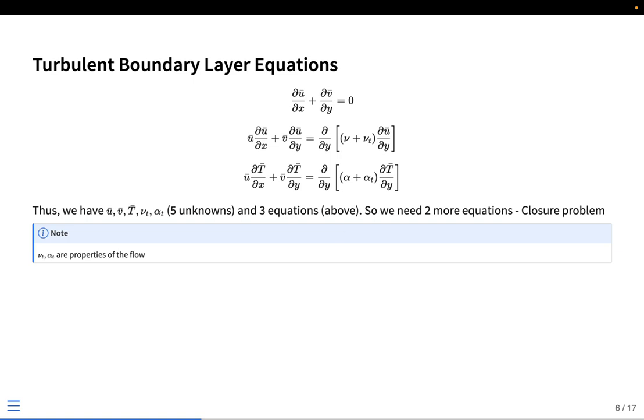But here, in addition to the normal viscosity term, we will have one additional term, that is the eddy viscosity term. Similarly, we will also have an additional thermal diffusivity. The energy equation also changes, with the turbulent thermal diffusivity alpha t getting added to it. Other than that, the remaining equations appear similar to the form that we had before. The only difference is that the quantities we are finding here are representative mean quantities.